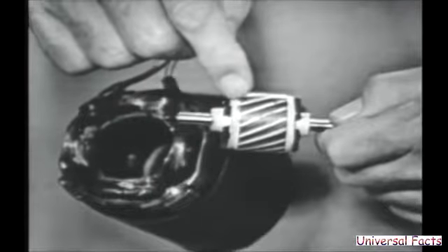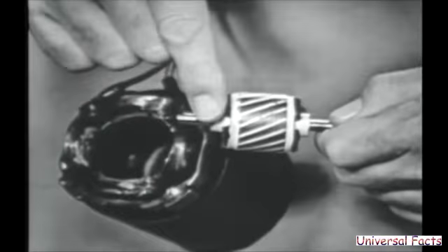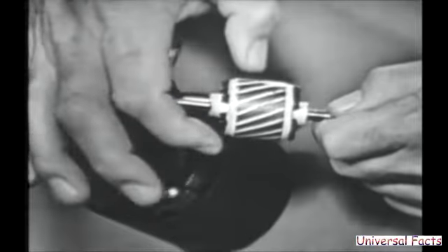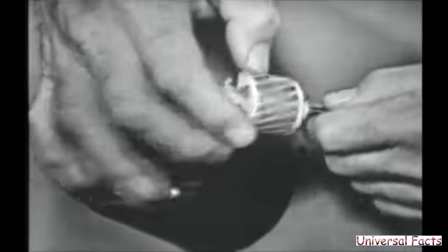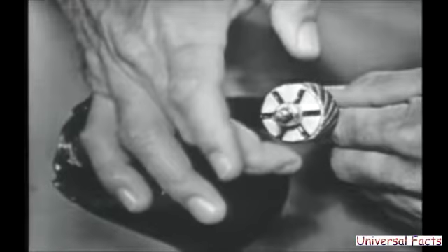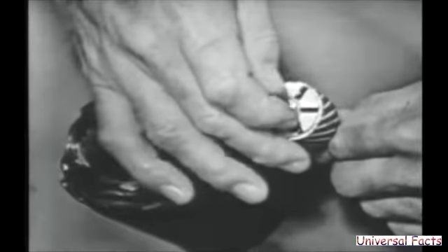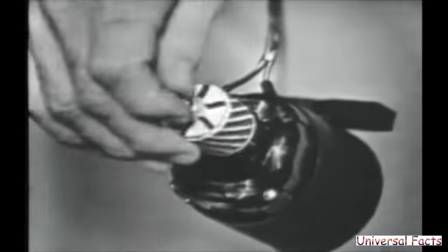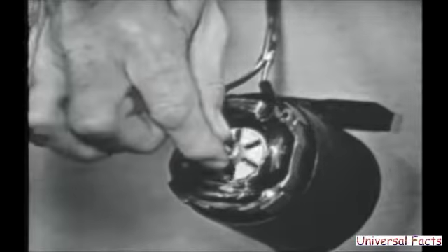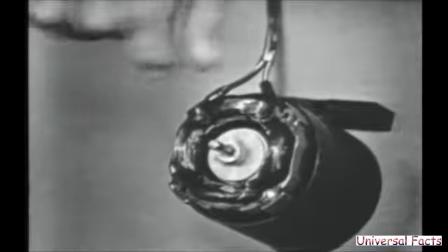Now, as the rotating field goes around this rotor, current is caused to flow in the rotor, which sets up a magnetic field, and the rotor develops a north and a south pole. Once we magnetize the rotor, it has got to follow the rotating magnetic field, as you've already seen, just like that. Okay? That's it.